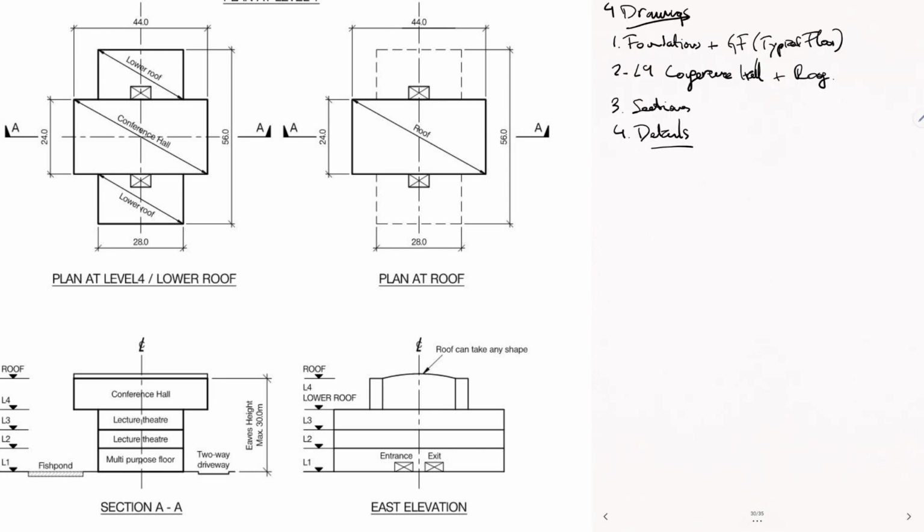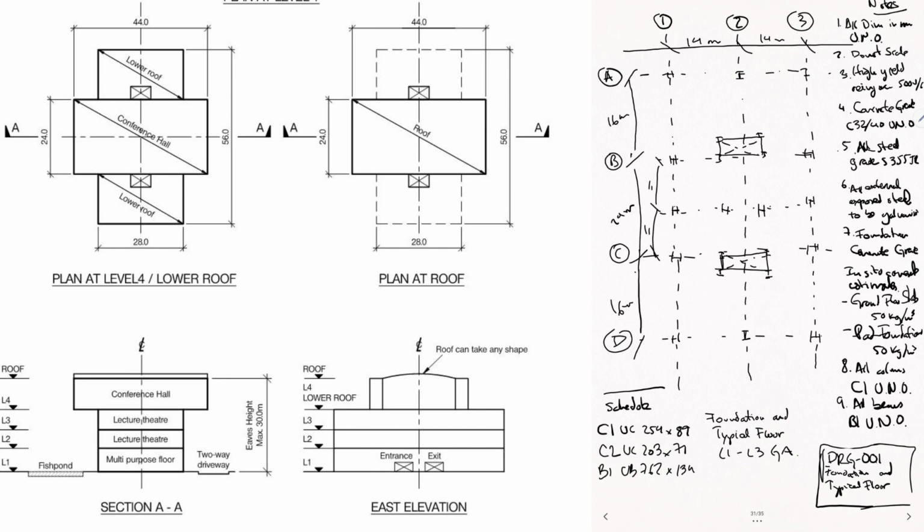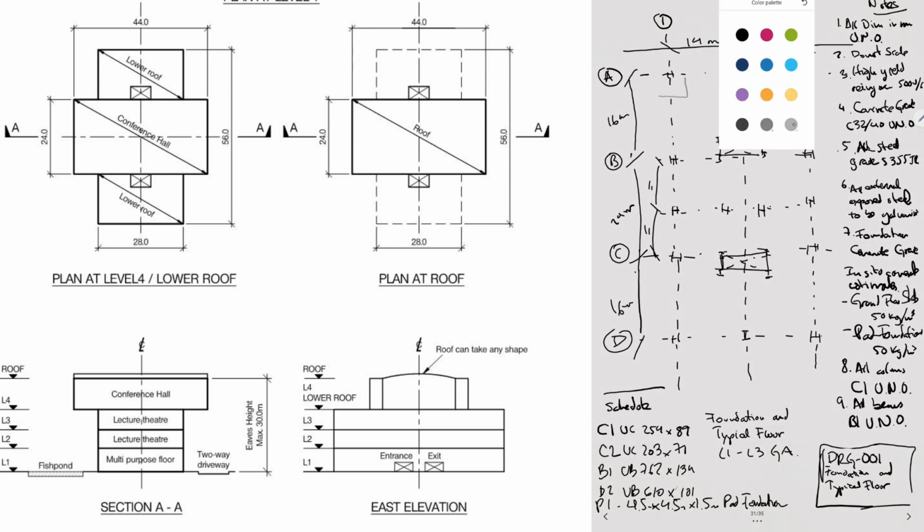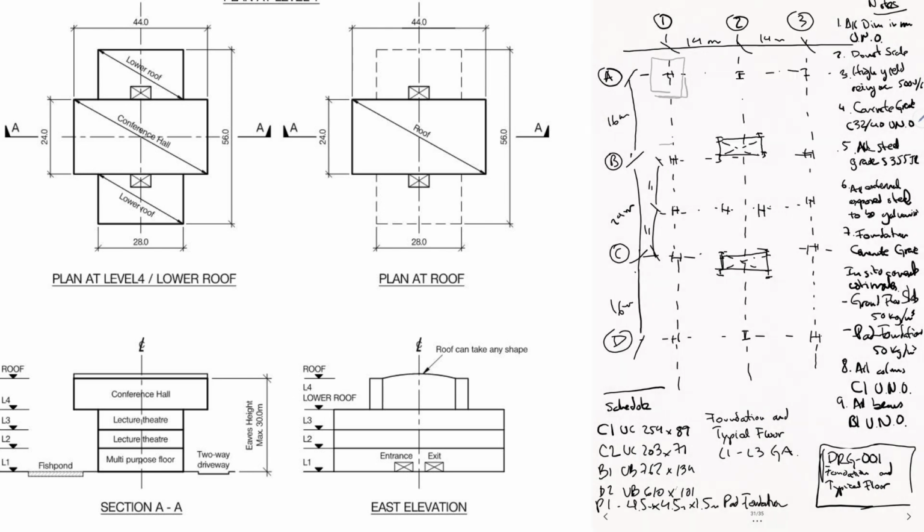So when you draw the plan drawings, the first one and second one, and I think in this case I did 3 plan drawings, I make sure that I use symmetry lines. Symmetry lines are your best friend in the drawings, because they basically allow you to have 2 drawings in a single page and done, well, more easily. So you got 2 drawings done in a single page.